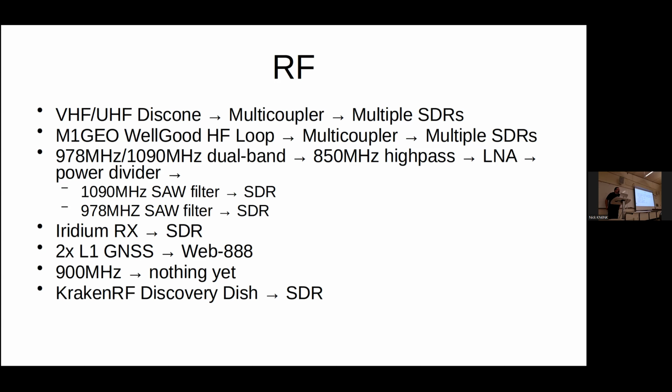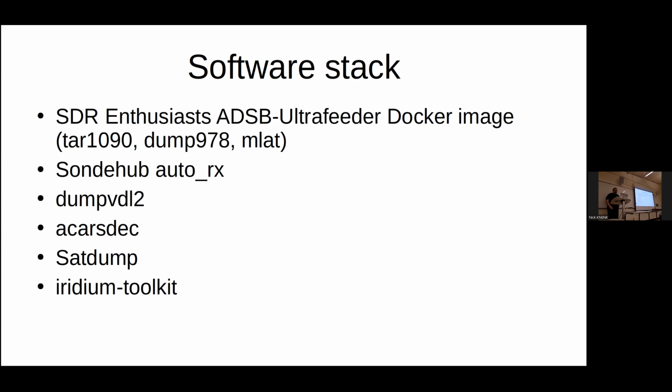Is the board in this case a PCB? Yep. This one I found in a park. It just had pads for 0805 size components. Nice. I also threw an anti-parallel diode on the input to help dissipate static before it hit the LNA. So that's kind of the RF path, just a bunch of stuff shoved through.